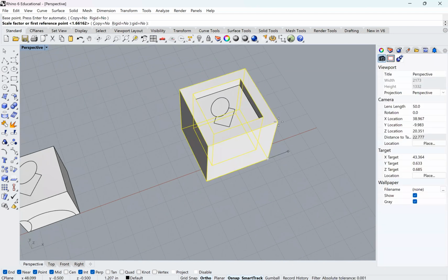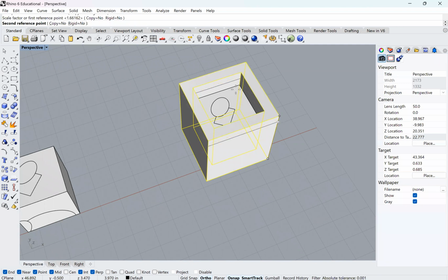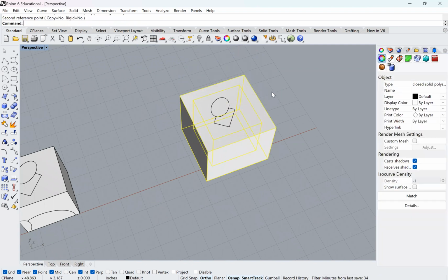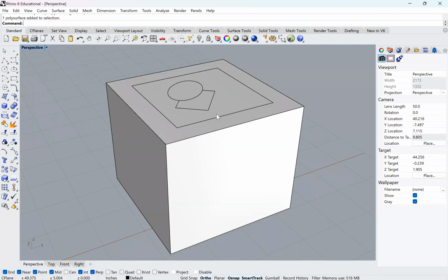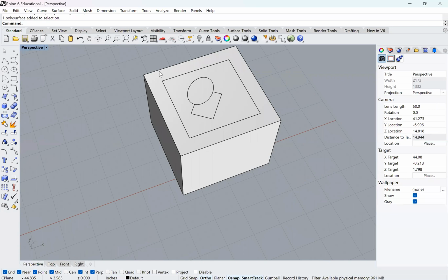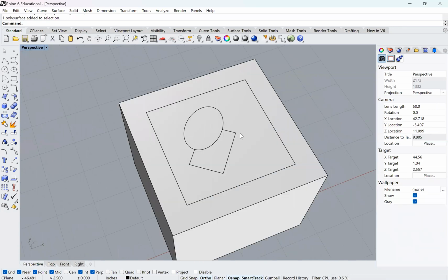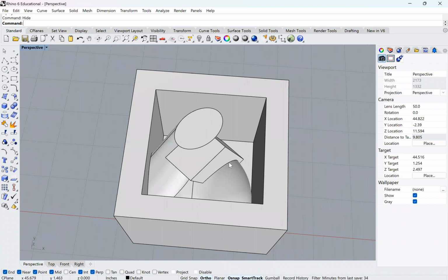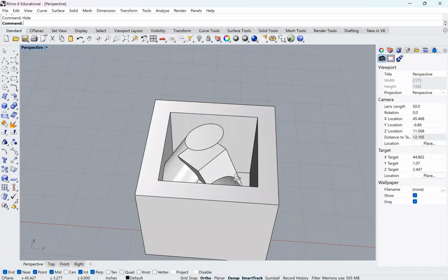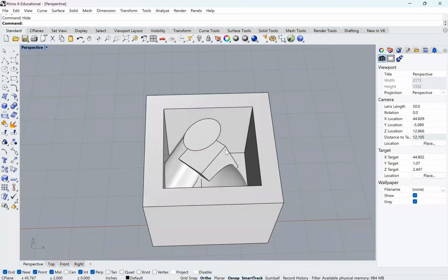So we can imagine here that we're going to have a wooden box that is larger, so that the interior volume is the exact size of our cast piece. And so we're basically going to do this, right? We're going to take that wooden box, put our little 3D printed objects in it, and then from the top, we're going to pour plaster, right?